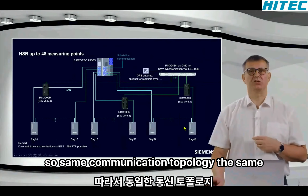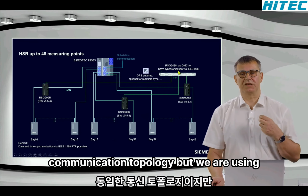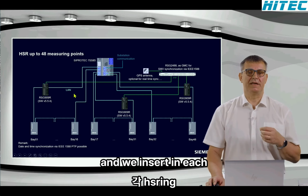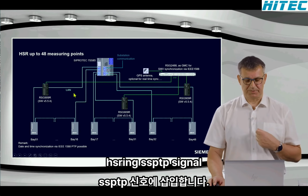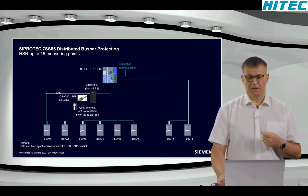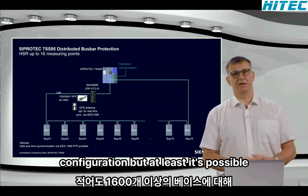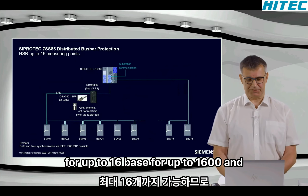So same communication topology, but we are using a grandmaster clock synchronized with a global time network like GPS, and we insert in each HSR ring this PTP signal. If we have only one HSR ring for smaller configuration, but at least it's possible for up to 16 bay units, for up to 16 current transformers.